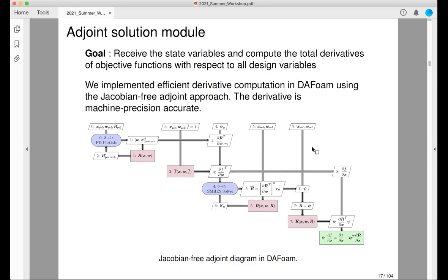Right. So if you are familiar with the implementation of CFD, in a steady state CFD, say I run a CFD, I need 1,000 iterations, right? In each iteration, you are using some methods, for example, some linear equation solvers, to converge the residual to 0, which means that you do need to compute the residuals, converge the residual to 0, and go to the next step. So in this process, you are computing the residuals. So we have already identified some functions to compute the residuals, instead of resolving the flow.